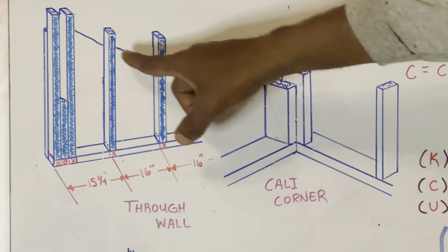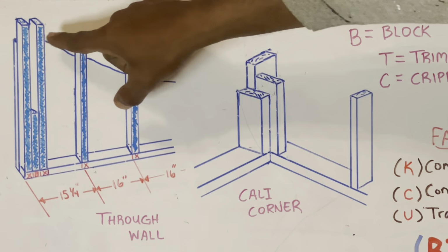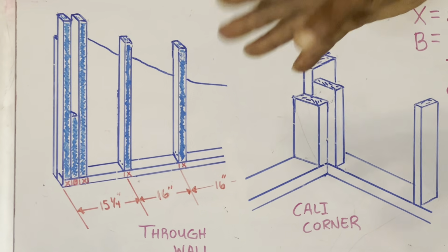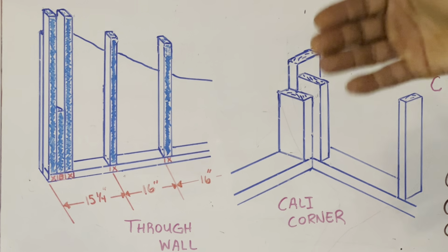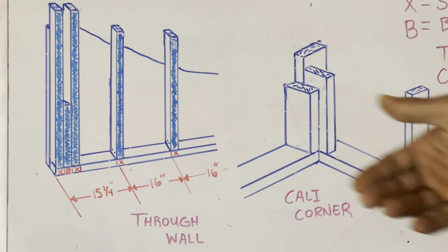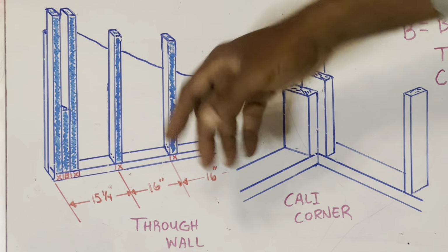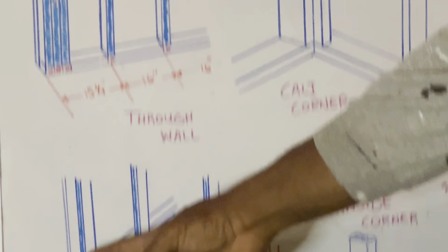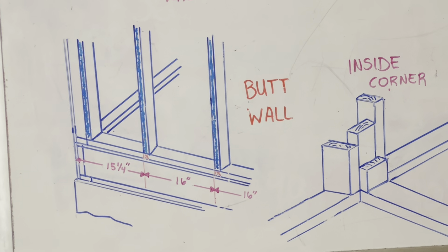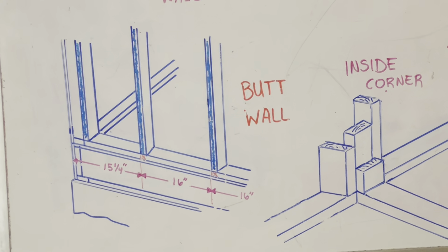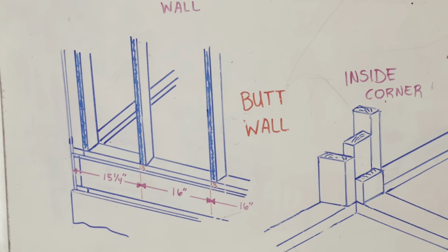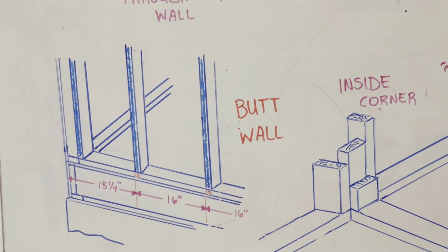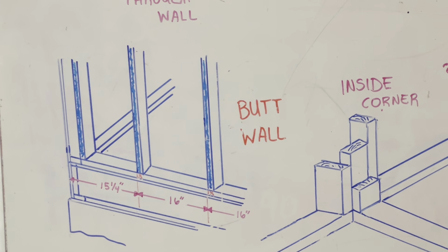Look right here, you see this on the outside, try to depict this sheathing that's going to be on the outside. You can see that 3/4 sheathing that goes on the outside of your structure. When you're framing, you frame your home, then you sheathe it up, so the outside is going to be closed up. So when you put your butt wall up against here, it closes up your cavity. Now you've got air right there in that space, which an air gap does contribute to R value, but it's still weak.